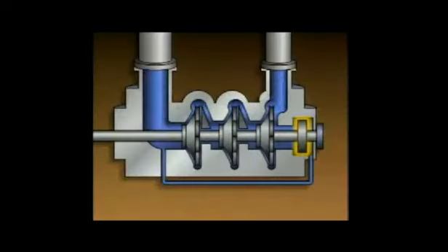On some pumps, a bearing is used to offset the thrust. In other pumps, a device known as a balance piston or balance drum is used. The pump in this illustration has a balance piston. Some of the fluid leaving the pump flows along the shaft and exerts pressure against the balance piston. That pressure tends to force the pump shaft away from the suction eyes and reduces the total thrust. Any fluid that passes by the balance piston is returned to the suction side of the first stage.